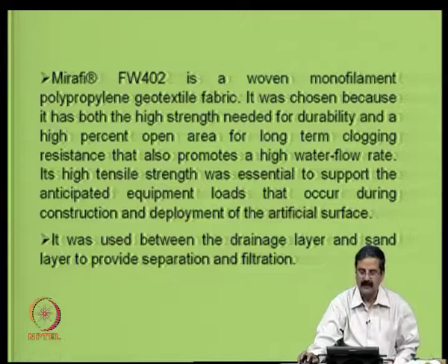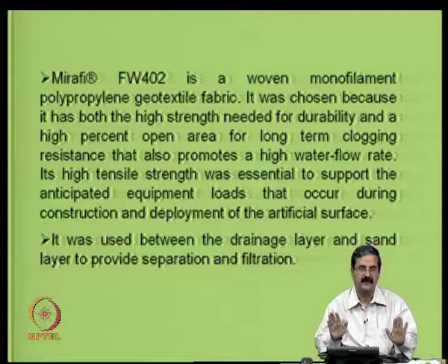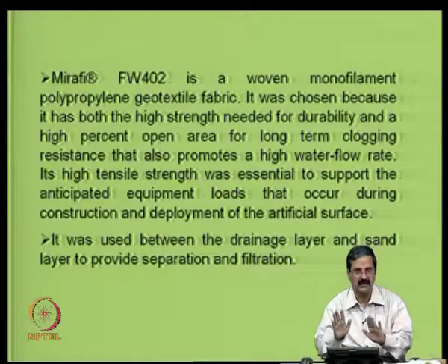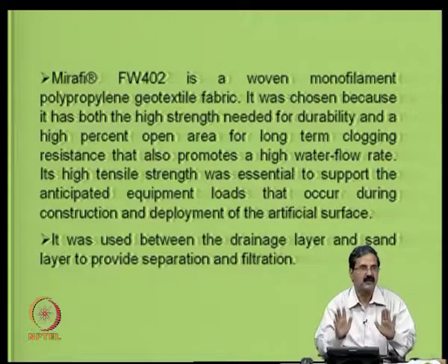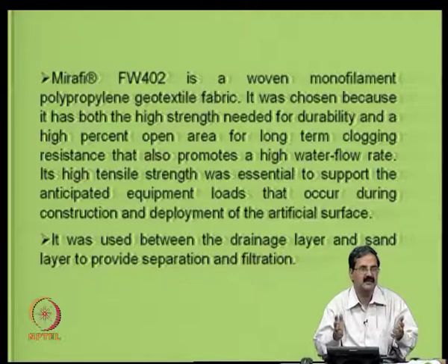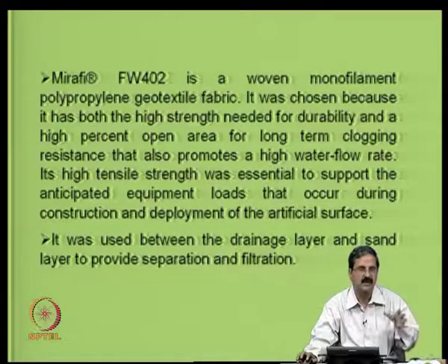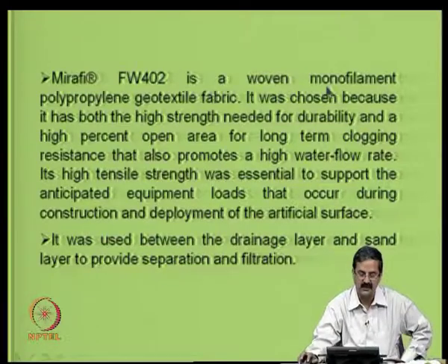The other day I was showing you the difference between a conventional filter and a geotextile filter. The water flow is a very important variable. Porosity is one thing, but water flow is another thing. So, you may go for a highly porous system, but then it should also be stable. So, there are some issues. That is the reason why geotextiles are excellent as filtration materials.